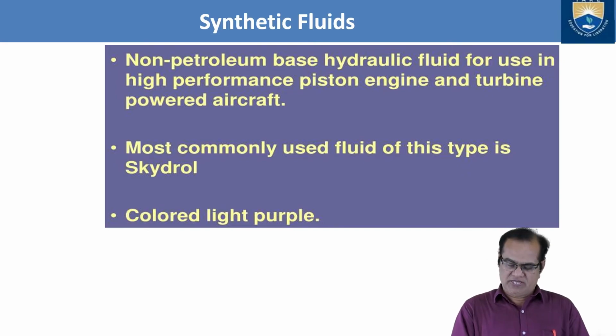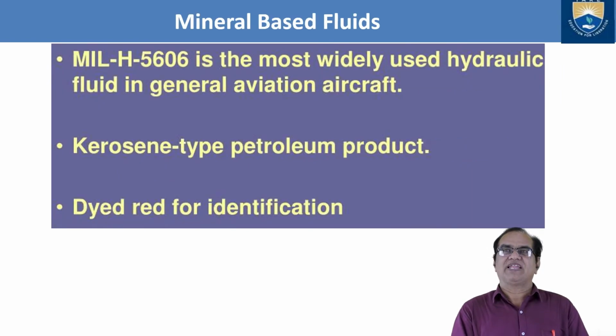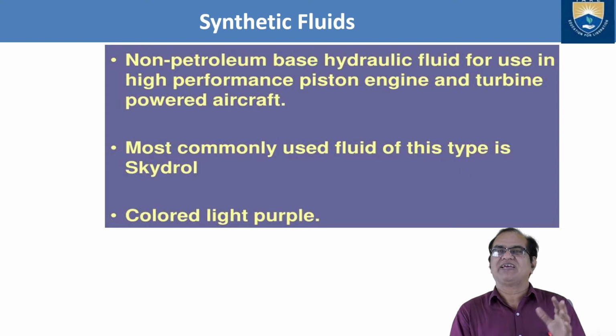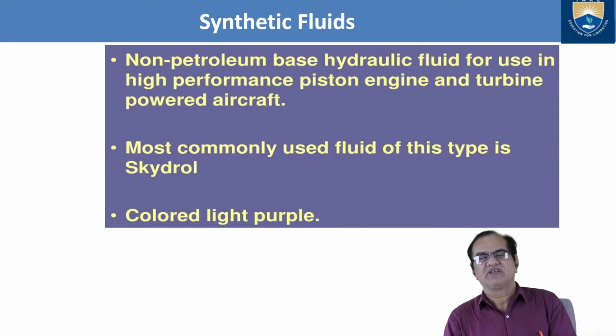If you see, the previous one is dyed red, but this one, the synthetic fluid, is purple in color. So by the color itself, you can identify that this is for the synthetic fluid and this is for the mineral. We should not mix synthetic fluid and mineral fluid, so you can identify by the color itself that this is the synthetic and this is the mineral.